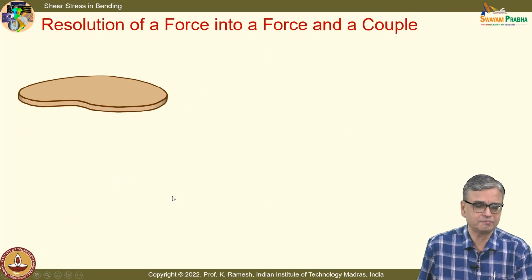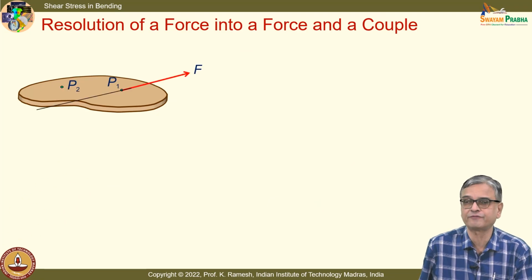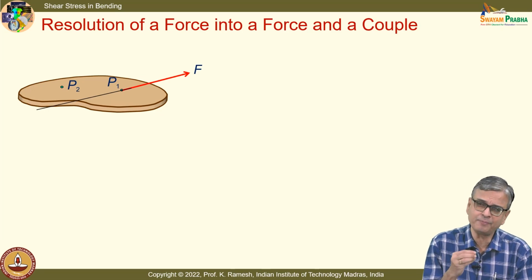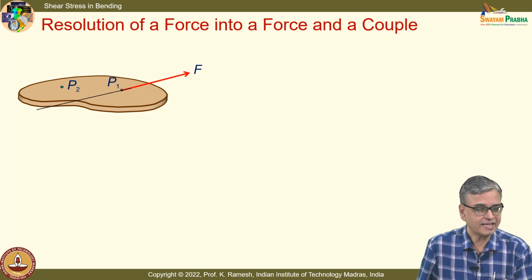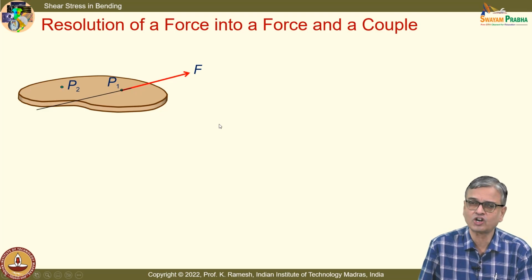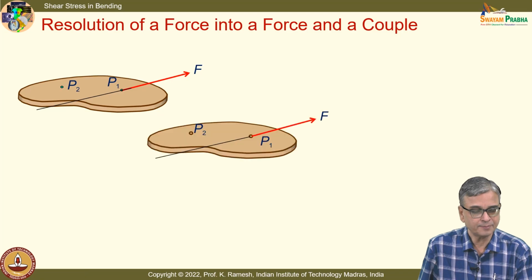And you know, I have been emphasizing that resolution of a force into a force and a couple is a very, very important concept. If you get that, many problems you can easily analyze. I can move this force along its line of action, no issue. The external effects are not changed. Suppose I want to move it from point P1 to P2, I cannot simply move it.